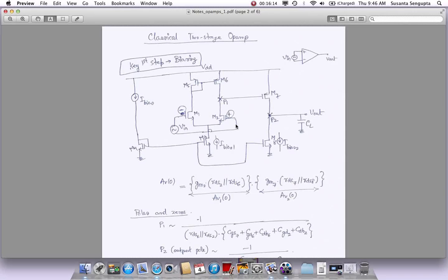So what I mean is, let's say this one was positive. Okay, if the output has to be positive, then if I trace it back, from here, if it's positive, this point will be negative because this is an inverting amplifier. There is an inversion. So this point will be negative. If this point is negative, this is again an inverting amplifier. You trace it back, then this point has to be positive.